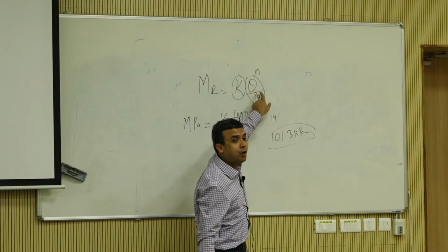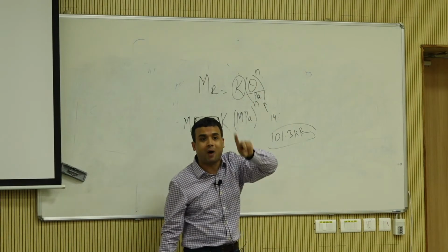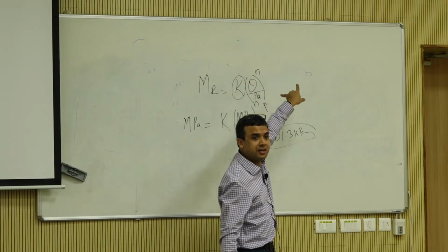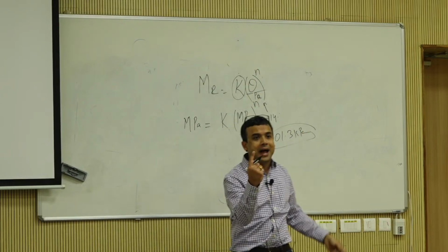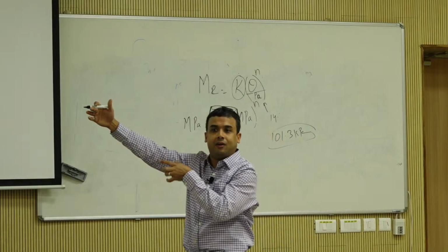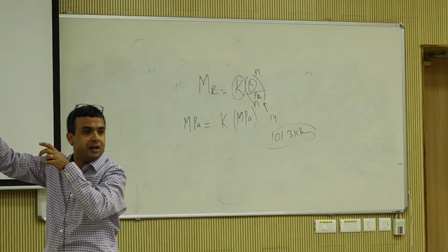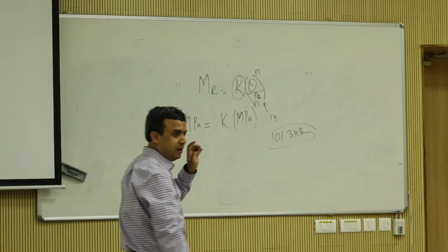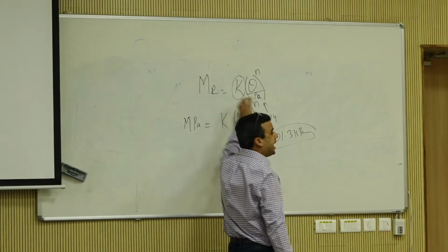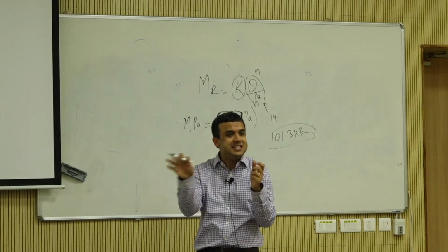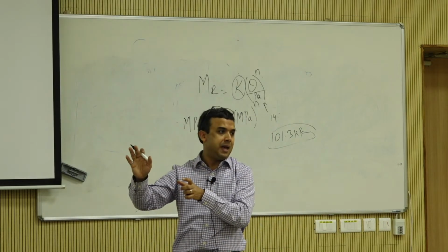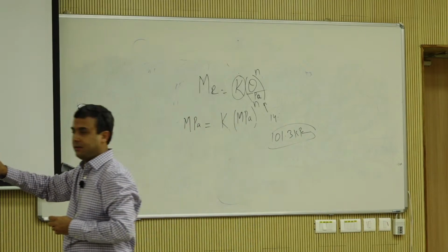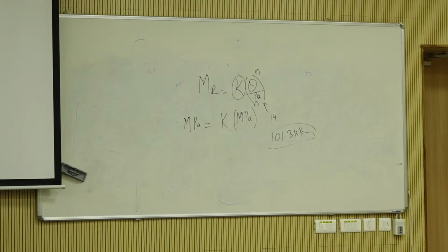For k theta, you always do theta over P0 because you divide by 1. Otherwise, you realize that your model parameter values are going to change, right? Whether you divide theta by 1, or by 101, or by 14.7, your model parameter values are going to change. So just pay attention to what you are trying to do. For k theta, it's more common to divide by P0, which is 1 kPa. You're just making it unitless. Okay.